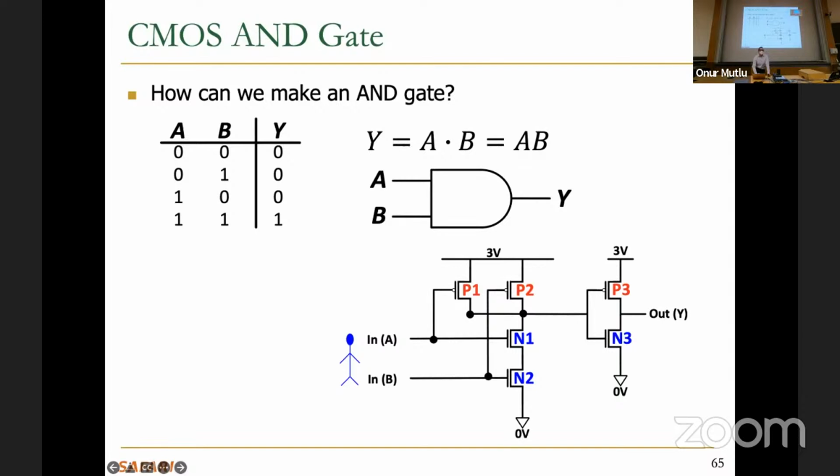You can try to do better, but if you do better, you're going to violate the operational principles of the transistors. Meaning, if you can come up with a circuit that may provide an AND to me, I can do it for you, but I'm not going to do it right now. You can think about it. But you have to put the NMOS transistors up and PMOS transistors down, and that's not going to work in CMOS technology. Make sense?